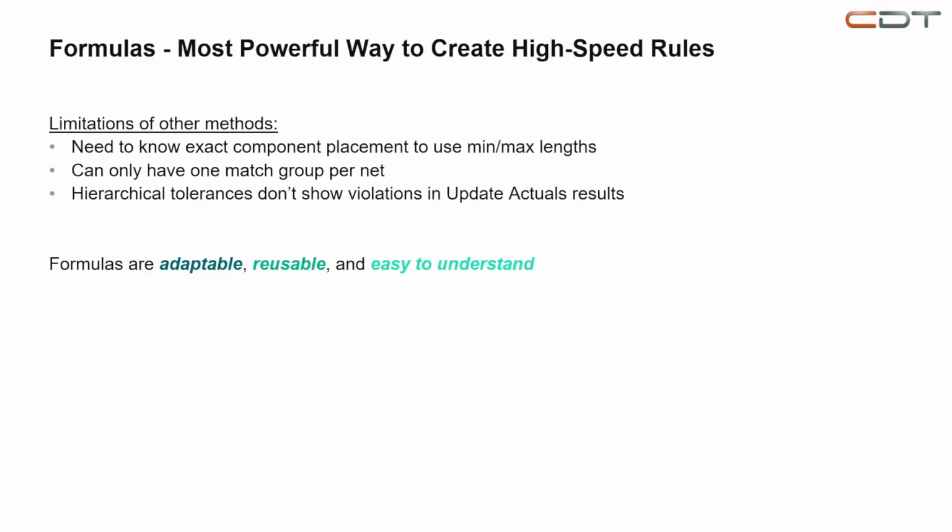And the nice thing about formulas is that they are adaptable, reusable, and easy to understand. They are adaptable because they change with your board. You are not using any absolute values because they are relative to other nets. So if nets get longer or shorter, they still would be applying.